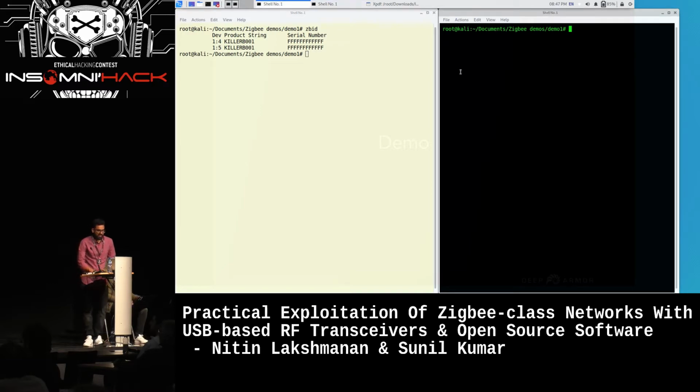In the beginning, or at any stage, the node will always be listening for the gateway packets. So first we will start the node to listen to the packets. For that, the KillerBee framework has provided a command called zbwireshark. And one more thing is that Zigbee-like protocols work at different channels. We are selecting channel 21 for our demo today. As I mentioned earlier, we are using 15 as the node, so I need to provide the ID number here.